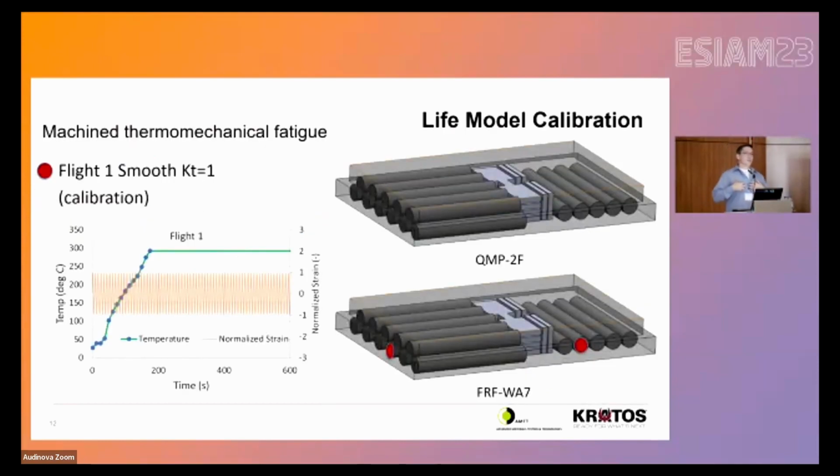Ultimately, though, I need to be able to predict not just the constitutive response, I need to predict the life of this actual component. So I can't show you the flight loading. I can basically say that there are two flight loadings that we are going to apply in an attempt to calibrate this life model. One loading has temperature increased to 300 degrees Celsius in a relatively short period of time. And it is load controlled, strain controlled, variable amplitude, can't discuss. It looks like fully reversed on purpose.